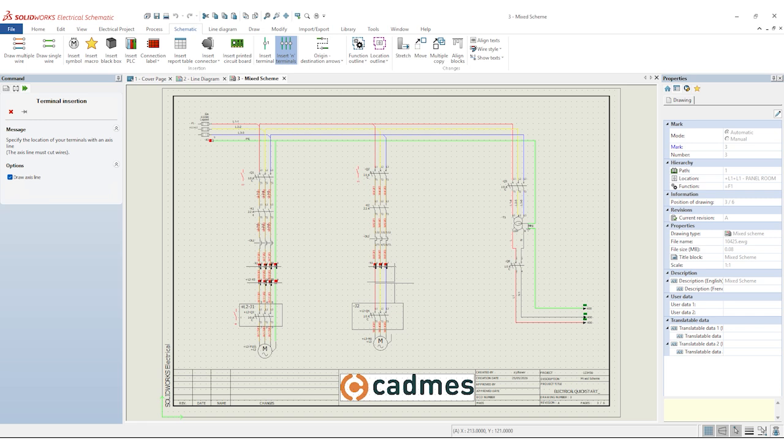Okay. Normally this would be me just drawing individual lines, but here it's smarter than just dragging each phase and connecting it to my symbol. With SOLIDWORKS Electrical's Quickstart, we can now draw in all three phases at the same time, and they connect automatically. The system snaps everything into place, it keeps everything aligned, and it understands the connection logic. So I'm not guessing and I'm not fixing later. I'm building everything right now as we move along, one complete circuit.